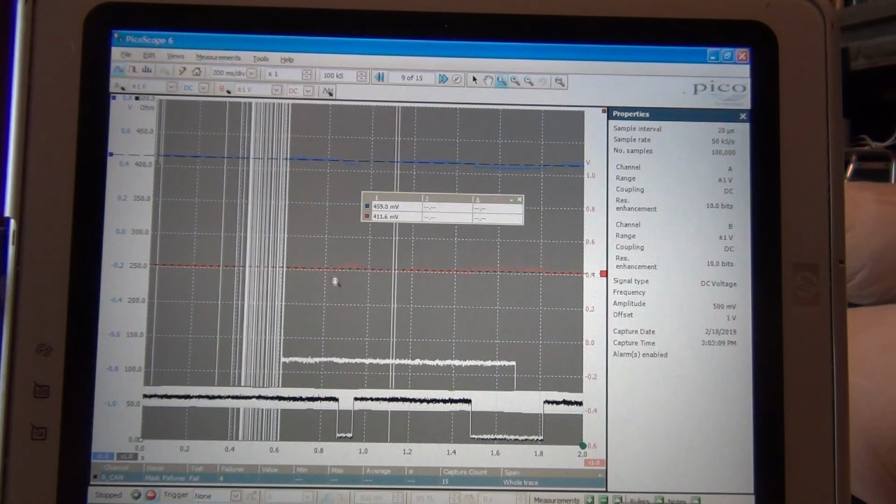Okay, so on screen number 9 we see that the resistance value drops almost all the way to 0, which corresponds to CAN lines being shorted together. Very nice capture. Not that much difference on channel A or B, but resistance values we can see change loud and clear.